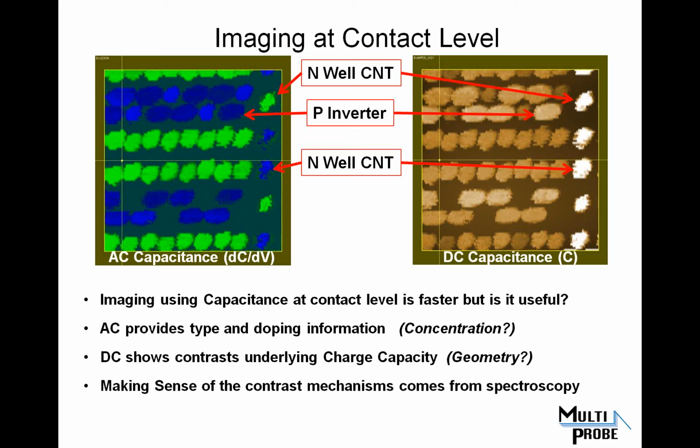So going on, you can see some contrast differential between contacts. In fact, I would point out these two down here. You can see these two little inverter contacts show a different signal level in the AC curve, and as does another one over here. And probably if we change the contrast a little bit, you'd see subtle differences between them. That's very, very similar to the kind of results that we normally get by doing picocurrent imaging. And I think that in the future, people will use that to point out where a suspect failure would be.